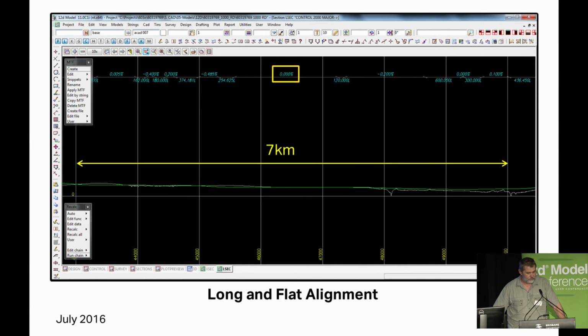One of the other challenges we typically face are the generally flat longitudinal grades on many of the Queensland motorway projects I've been involved in over the years. And developing and applying superelevation safely requires a bit of understanding of identifying potential problem areas early in the design process so that you can plan accordingly.